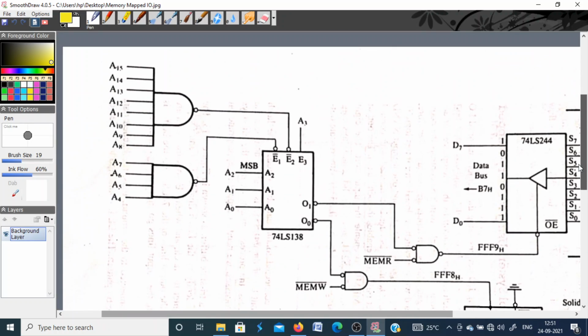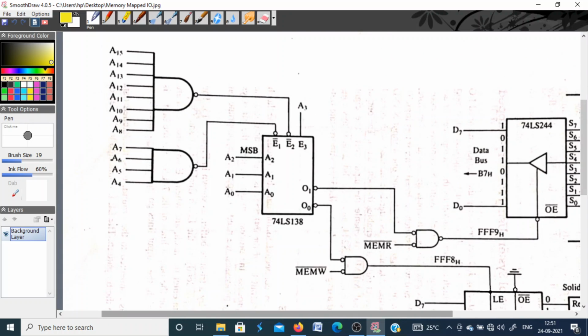See, what we have used here is an instruction. We use again a decoder here. Okay, so all the 16 address lines are now used, and we will use the same decoder for interfacing with the input port and an output port. First, let us see what is the input output port address that we are using.